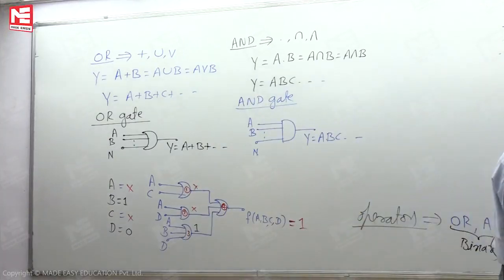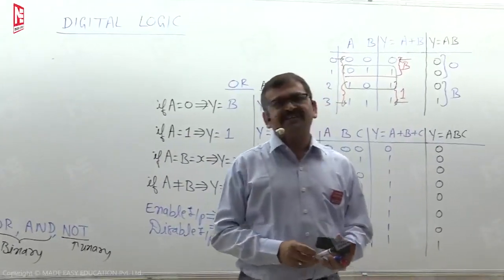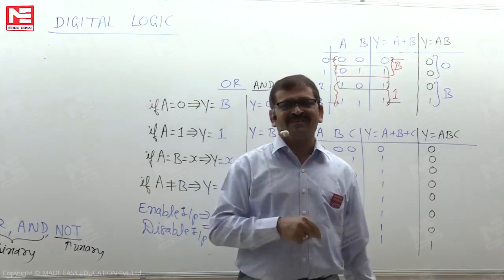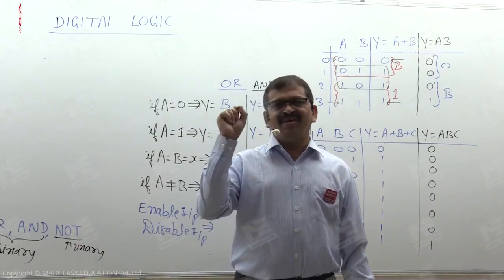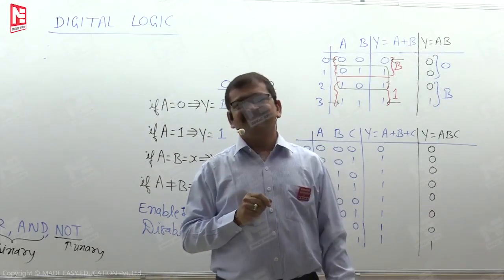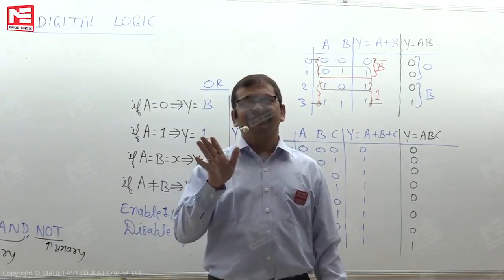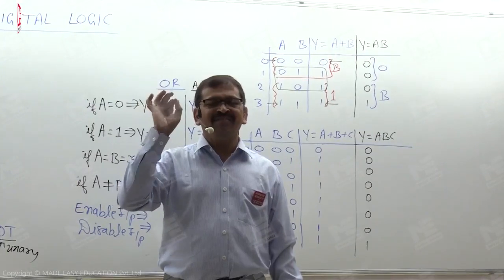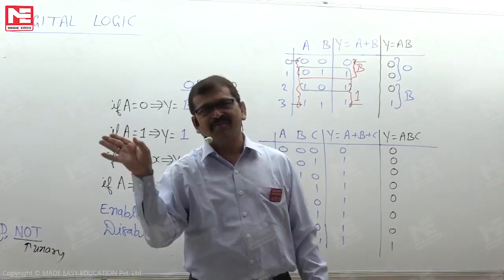If you remember well, I can quote a slightly higher level example. In the case of sequential circuits, we use the clock signal. Until we provide a clock signal, the circuit, in the normal situation I am talking about, will be in an inactive state. The circuit may have any number of inputs, but until the clock input is 1, the circuit does not get normal operation.